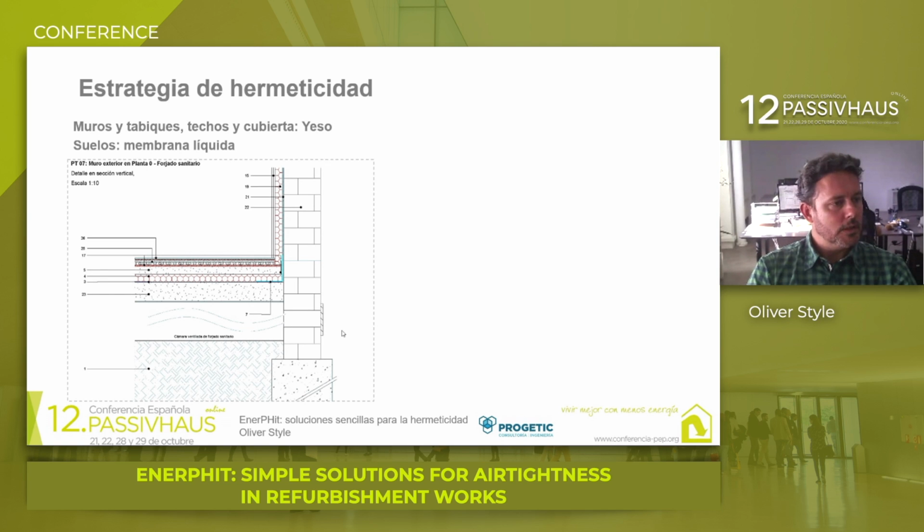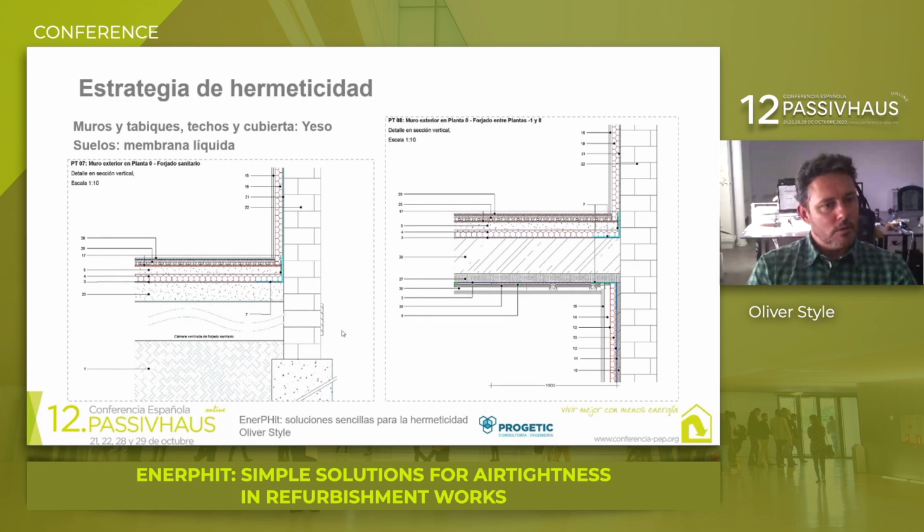Cellulose insulation was projected on the walls on galvanized steel profile uprights. The profiles were slightly separated from the wall to avoid creating a thermal bridge, and with double plaster board finishing before applying finishing in the installations, and then a cellular glass insulation was laid on the flooring. The materials were chosen based on environmental impact criteria, because the building was also certified for that purpose.